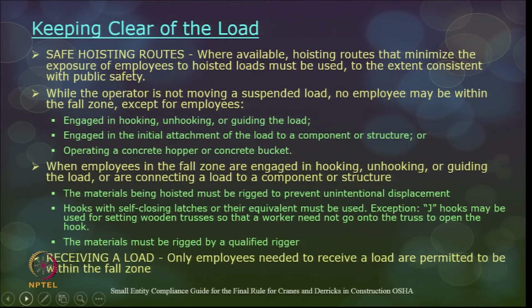When employees in the fall zone are engaged in hooking, unhooking or guiding the load, the materials being hoisted must be rigged in order to prevent unintentional displacement. So, the material should not be moving here and there. It has to be completely packed and so on. We will see what the rigging practices available are.